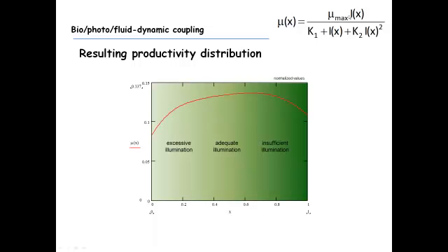But going further, we can also integrate IBA's model now, replacing the intensity of light in function of the distance from the light source. Here we get the productivity rate in function of the distance from the light source. And when we replace all the formulas that we obtain here, we obtain this red curve here, which is also a normalized value, because the idea is just to show you that you have 3 distinct regions inside a photobioreactor.